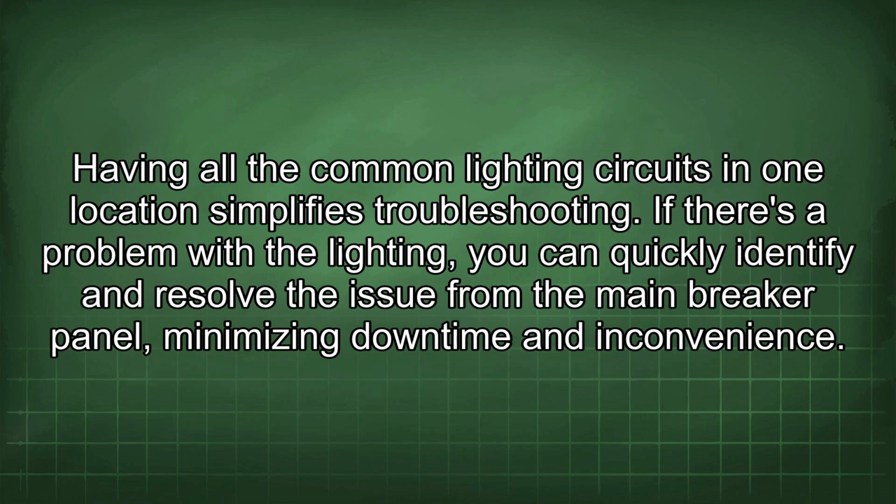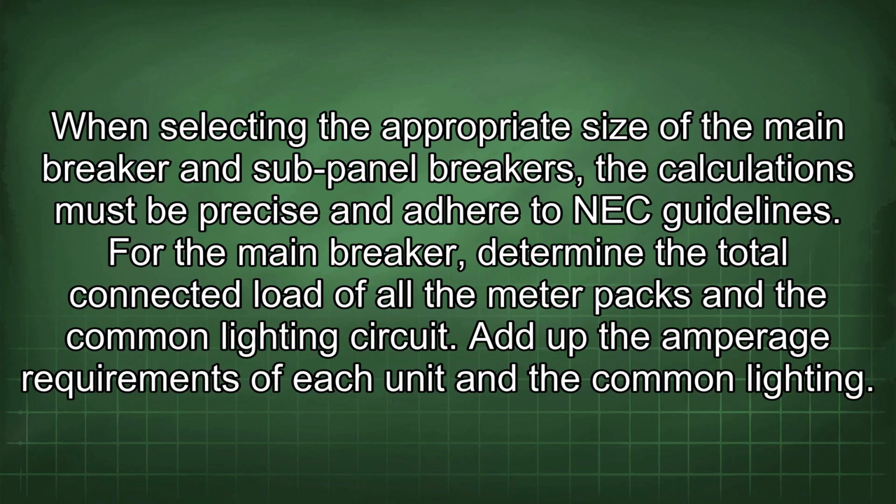Having all the common lighting circuits in one location simplifies troubleshooting. If there's a problem with the lighting, you can quickly identify and resolve the issue from the main breaker panel, minimizing downtime and inconvenience. When selecting the appropriate size of the main breaker and sub-panel breakers, the calculations must be precise and adhere to NEC guidelines.